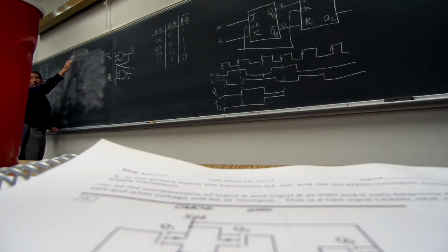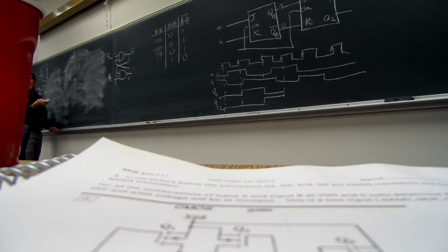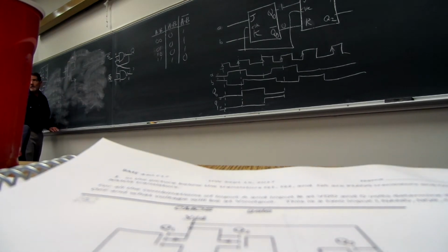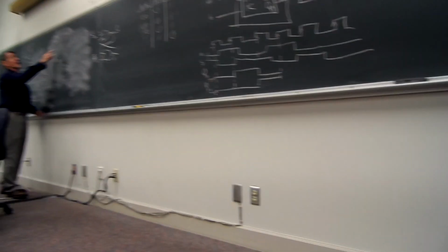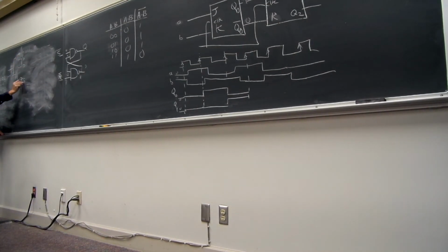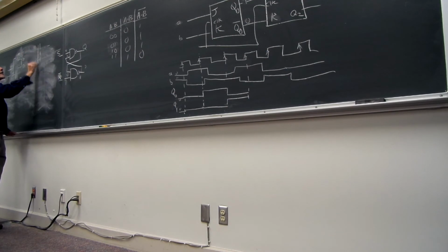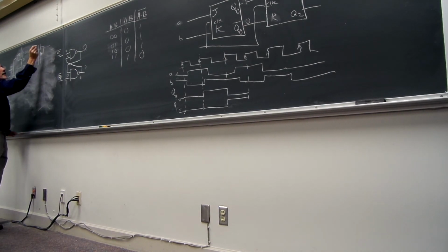This is what kind of a device up here? PMOS. Where's its source and drain and gate? I'll give you the easy one, that's the gate. Where's the source? Source is at the top, it's always associated with the arrow, correct? This is the drain, how about this guy? Drain, this guy. Now, a little bit different nomenclature on these guys here. They're using, instead of a configuration like that, it's showing like this, and this guy on the P channel is coming out.